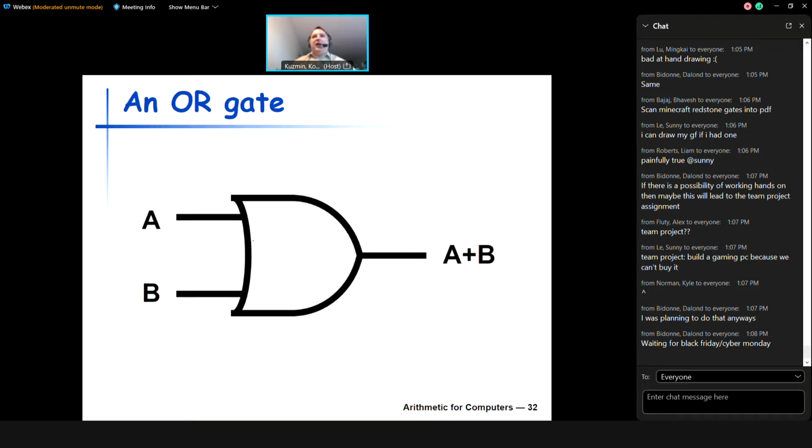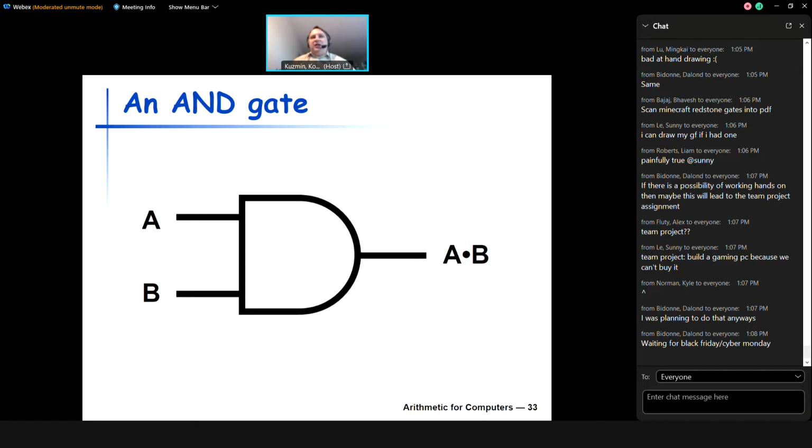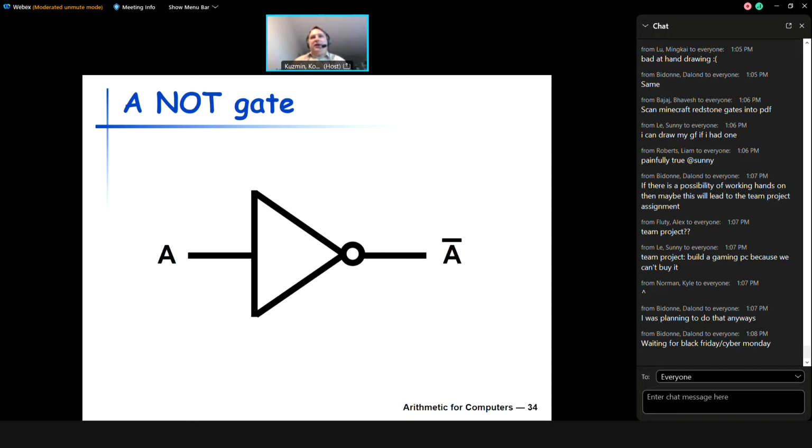All right. Now the important thing is their notation. To distinguish between those boxes, we use slightly different shapes for them. So this is the shape for an OR gate, right? The inputs are on the left, the output is on the right. So this is the OR gate, and this is an AND gate, so that we can visually, easily distinguish between the different types of gates. And this is a NOT gate, or negation or inversion.